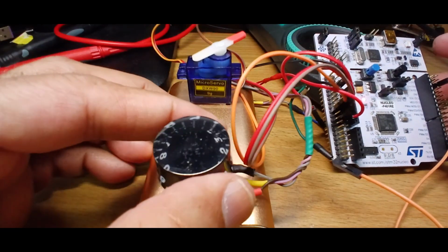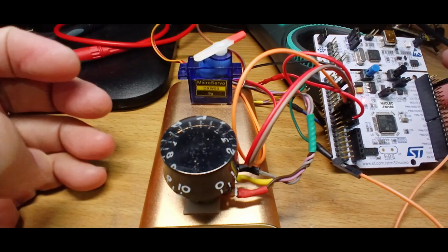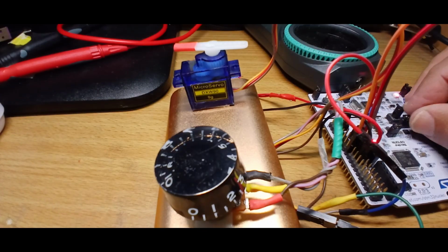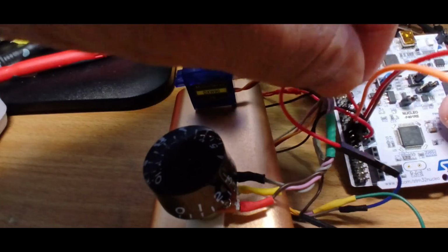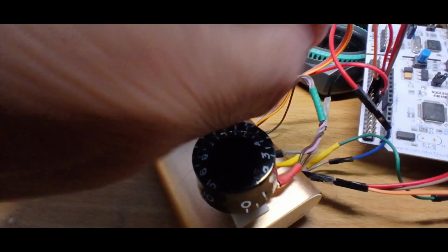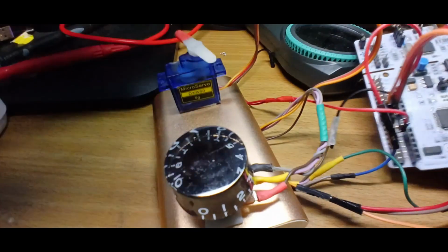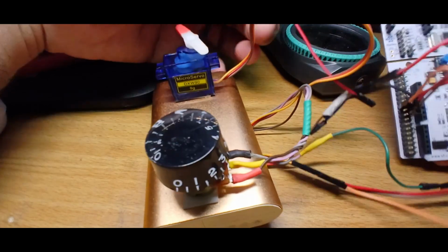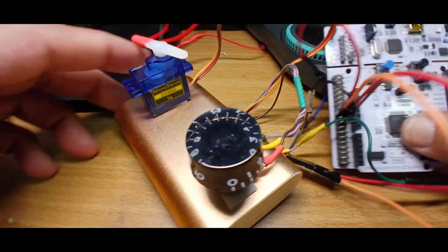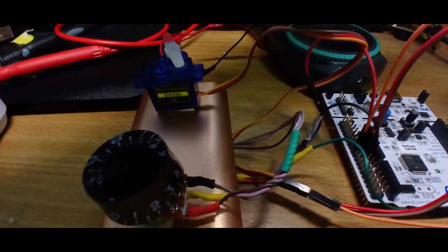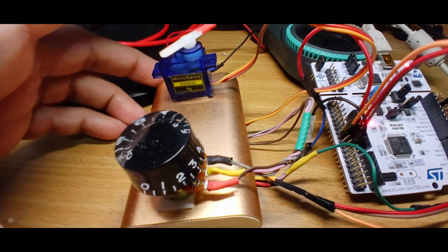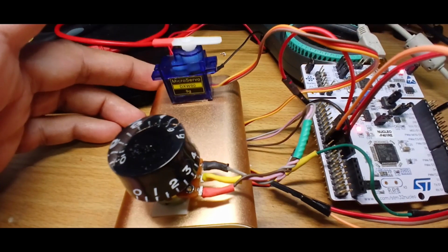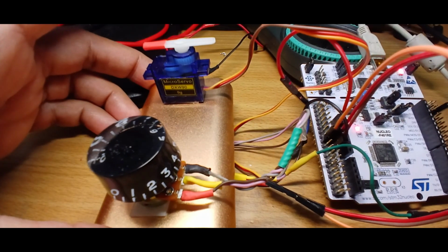When it is connected, then you can move your potentiometer. So it is connected from here. Okay, I will change the jumper to the original setting. Also I will remove the ground and the VIN pin which is going to the 5 volt. So now there is no power from the external supply. I will connect with the PC. Now it is connected from the computer. So now 5 volt is coming from the U5V.